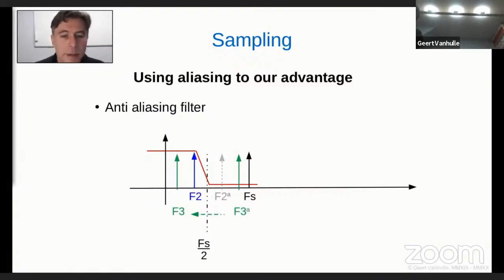Now, if we look at a sample frequency here, if we have an alias, and now we have the other way around, if we now have an alias that is higher in frequency than the f2 alpha, for example, f3 alpha, that is closer to the sampling frequency but higher than the f2, it appears mirrored below the f2. So between half of the sample frequency and the sample frequency, what we have is a signal rise in frequency. They are mirrored as a frequency that is closer to 0. So we get a flipping of the frequency spectrum in this range. So this is something to remember.